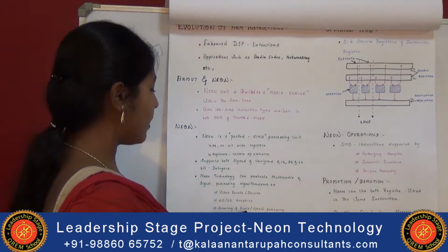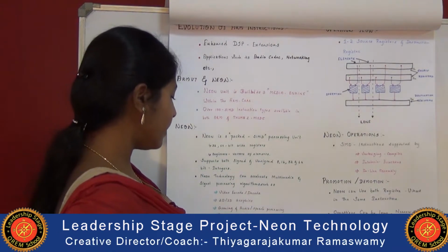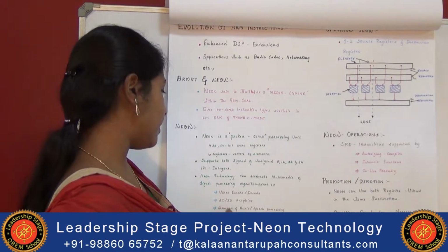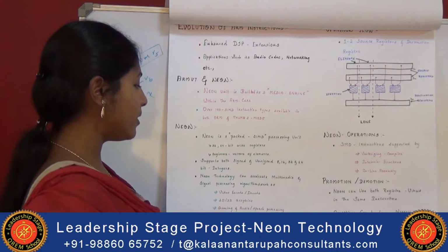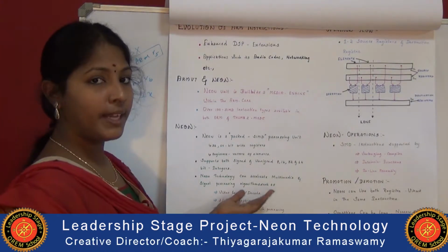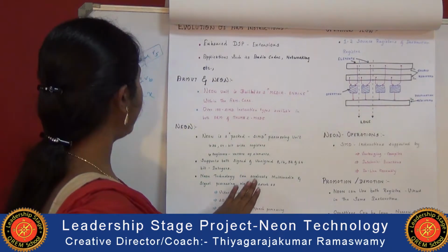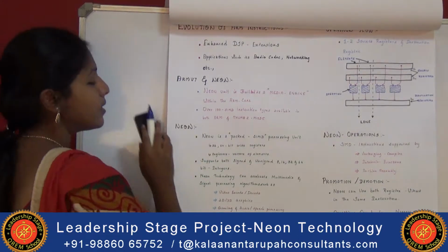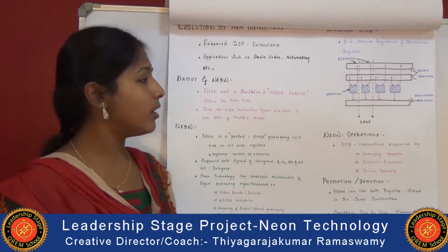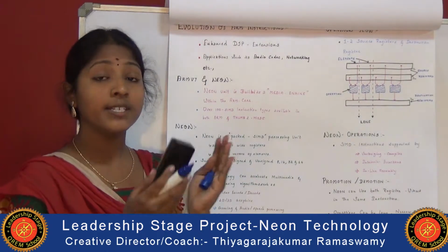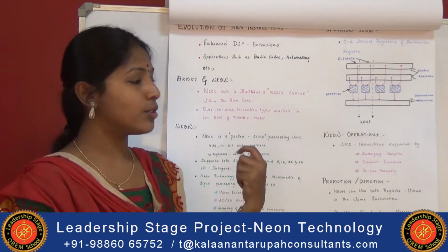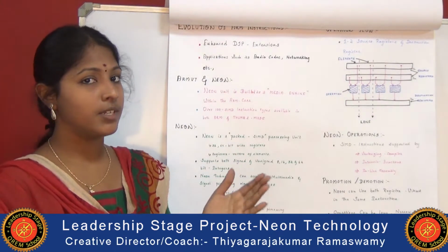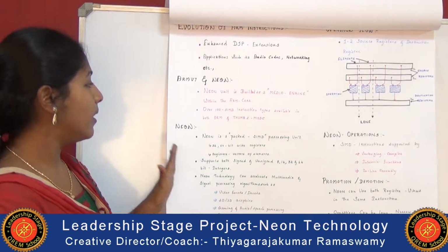So image processing and so on comes under this, that is color conversion or compositing, like that. And in video encode or decode, it is nothing but codec. It can be used for MPEG4 encode or decode. These are all the algorithms which are used here. And now this cleanly architected Neon technology seamlessly uses its own pipeline and also its own register file. As I said, a register file is nothing but an array of processor registers, and also the pipelining concept. That's about this Neon.